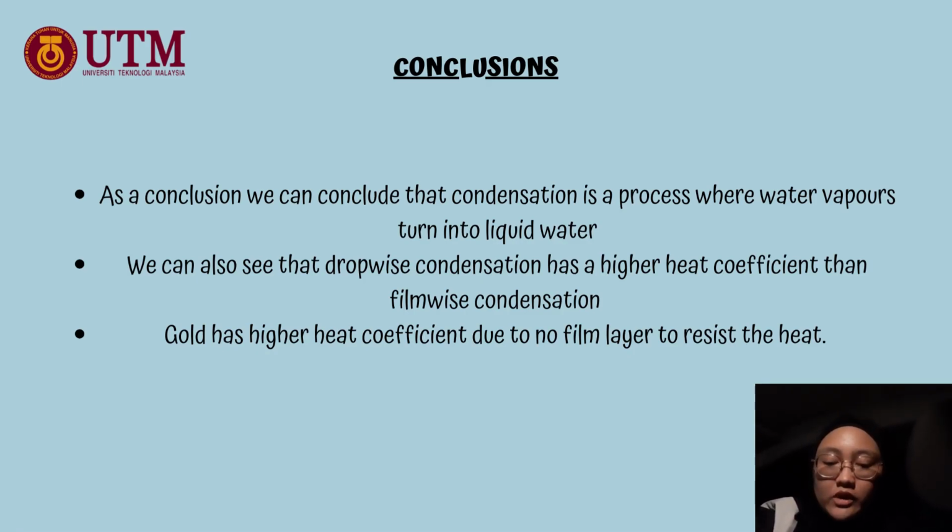As a conclusion, we can conclude that condensation is a process where water vapor turns into liquid water. We can also see that dropwise condensation has a higher heat transfer coefficient than film condensation. And lastly, gold has a higher heat transfer coefficient due to no film layer to resist the heat outside of the rod. From the calculation, we can also prove that the heat transfer coefficient for dropwise condensation is higher compared to film-wise condensation.